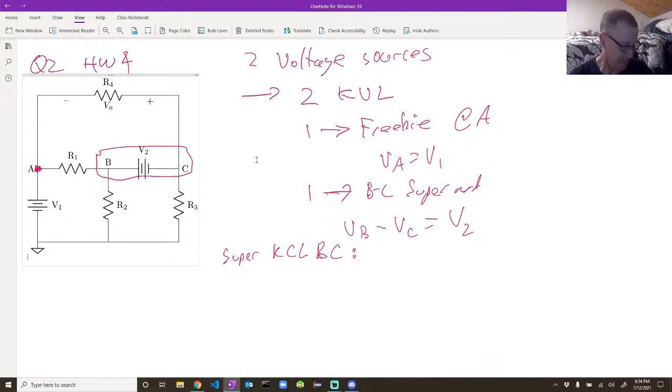Now, the thing with mesh currents when you're doing mesh analysis, and device currents when you're doing nodal analysis, is it's completely up to you which direction you choose to have the current flow, right? So the only one in this diagram where we're sort of forced to keep a particular direction is for R4. We've really got to have IR4 going that way because it's nice to keep the passive sign convention happening, because we've already got V out defined and its polarities defined. So we've got to say that IR4 goes from right to left.